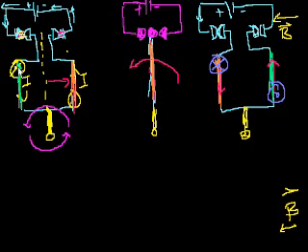So on the left-hand side, you always have the current coming down, and on the right-hand side, you always have the current going up, so that the net torque is always rotating this contraption down on the left-hand side and up on the right-hand side. Coming out of the page on the right-hand side and then down on the left-hand side. And you could actually turn a wheel now. You could create an electric car. So that is the basics, really, of how electric motors are created.